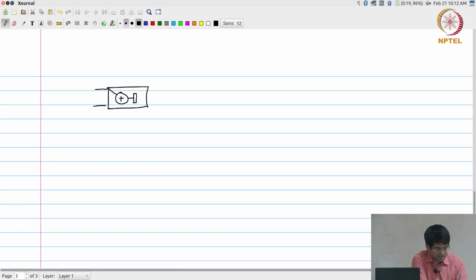All that I am saying over here effectively is, the two inputs over here, rather than drawing multiplexers, I am going to use a slightly different notation. I will use some kind of switches to basically indicate that these are switches that are sort of rotating across different phases, 0, 1, 0, 1, 0, 1 and so on, right. A multiplexer is how it is finally going to get implemented, but visually sometimes another way of looking at it is to think of it as rotating switches where you are just going through different phases cyclically. Okay. So, for that what we say is there is a phase 0 and a phase 1. Similarly, there is a phase 0 and a phase 1.